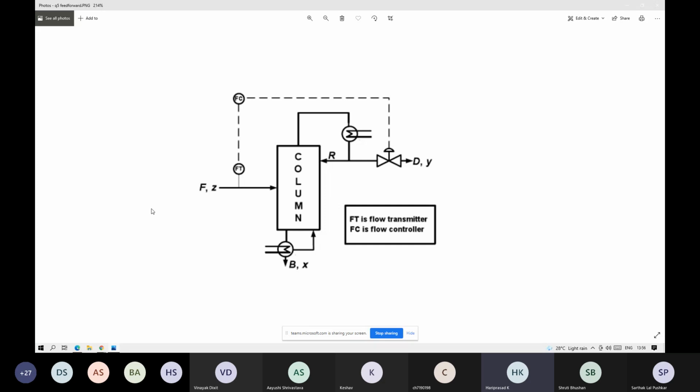The variable that you need to measure, or its related variable, would be measured in the feedback control, while in the feed forward you measure some variable in the upstream, and you would tend to anticipate what would have happened if they enter into the system and start taking the corrective action from that point onward. Okay.